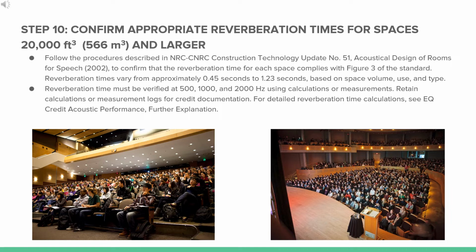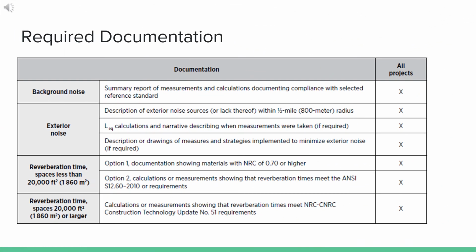Reverberation time must be verified at 500, 1000, 2000 Hz using calculations and measurements. Retain calculations and measurements logs for credit and documentation. For detailed reverberation time, all projects have the same required documentation as can be seen here.